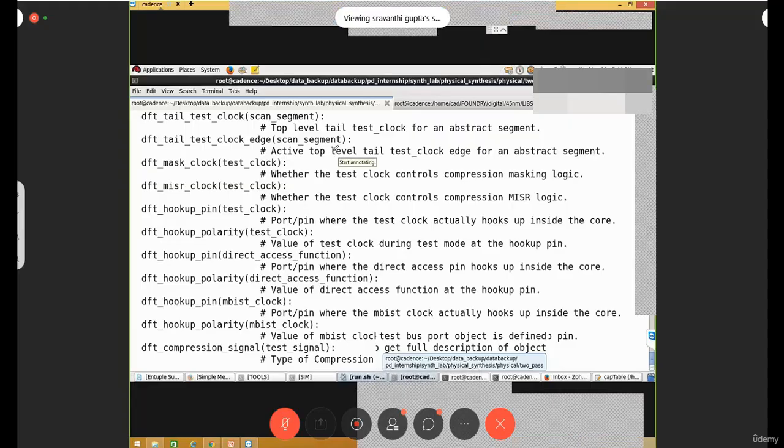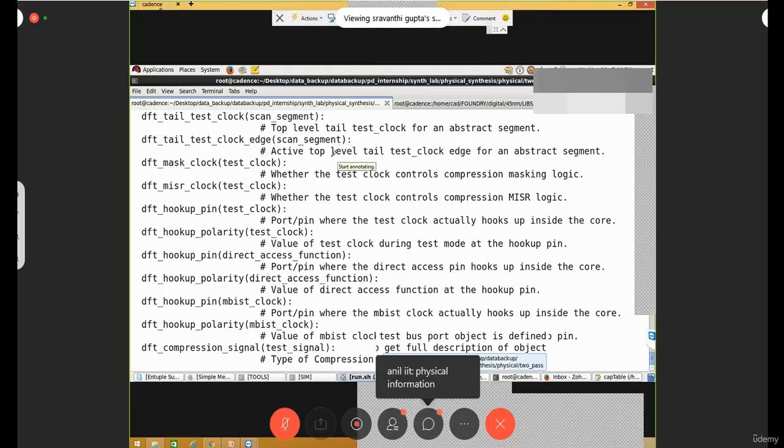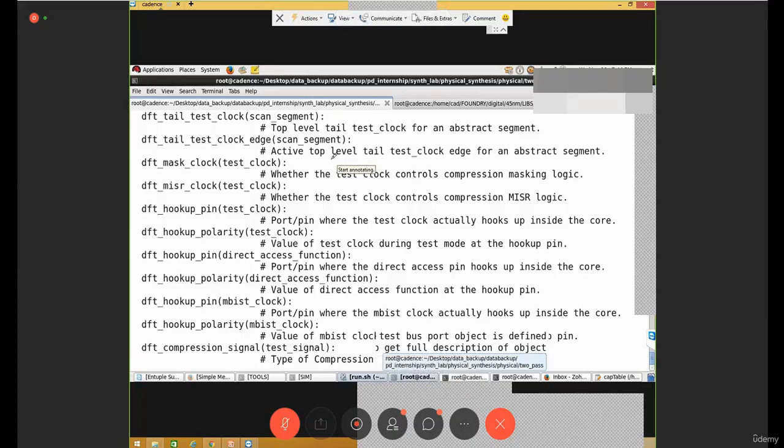Now, I told you the DEF file contains the pin attributes, I mean the pin location and the memory location, wherever it has been placed. The floorplan DEF usually consists of the pin information, where it is placed when taken to the floorplan stage, and if there are any memory objects in my design, where those memory objects are placed, and the area in which this pin placement has been done. In logical synthesis, you don't have any such information. That means you don't have any pin location, any memory location, or any area that is needed for the conversion to the gate-level netlist.